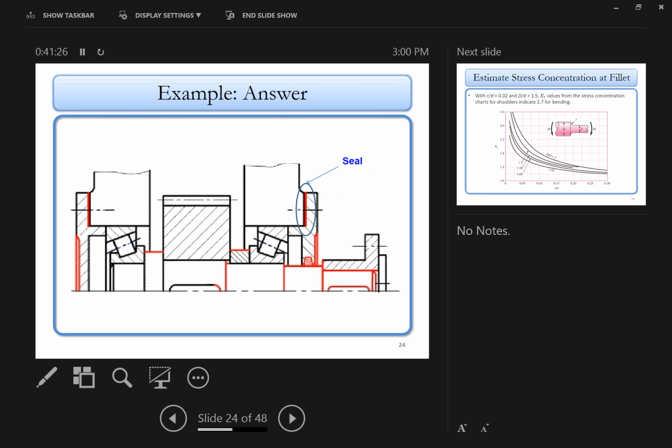So basically, you think there's very minimum expansion because of temperature, right? But otherwise, you should design one side to be floating. So this one here, as a matter of fact, has a little bit of floating. If you look at the bottom here, it's not very much, but it can move slightly along the shaft a little bit.